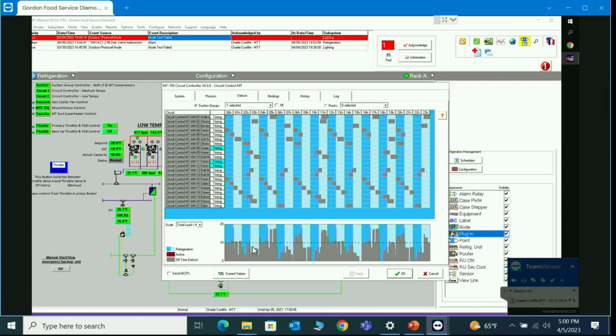Trevor, I think I'm understanding, if you have to maybe change hardware or change greatly the PID, and you want to reset the learning, there's actually a button that says reset the learning, and then you can start it learning from all of your corrections and not have the old stuff that was no good. That'll be gone, and now that you've corrected, it will start a new history and get smarter from that point of correction. So that is in there. It's in the advanced view.